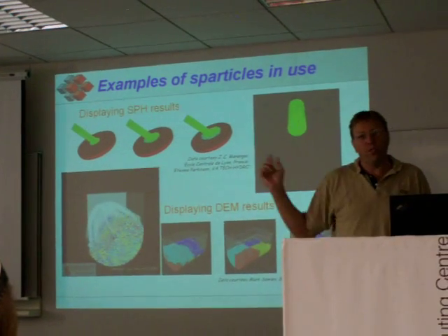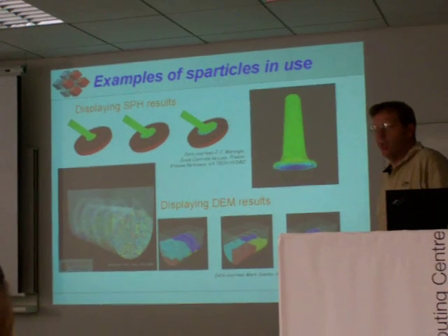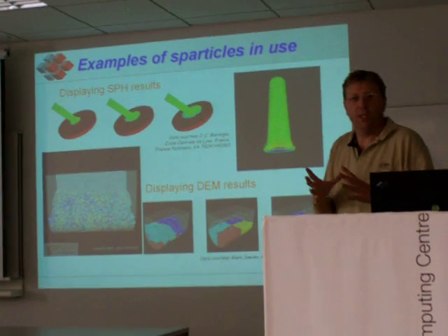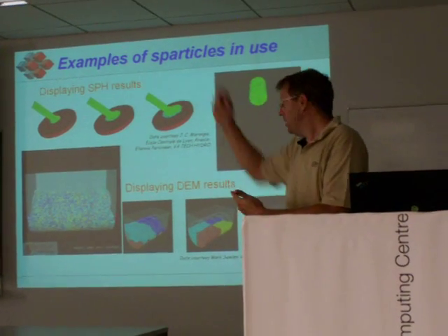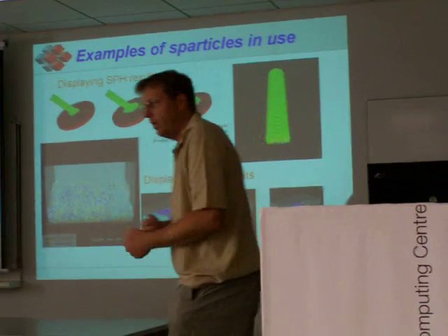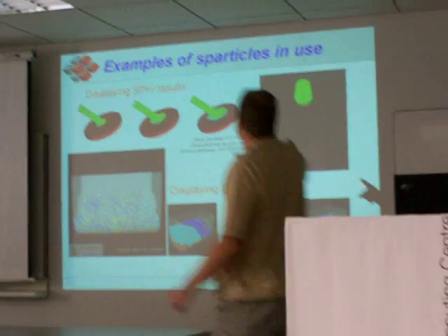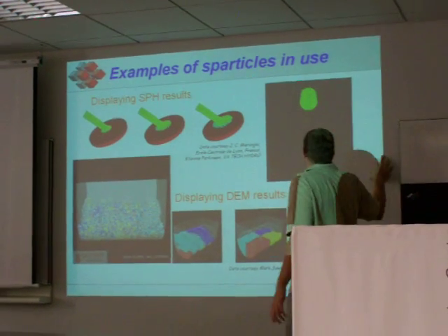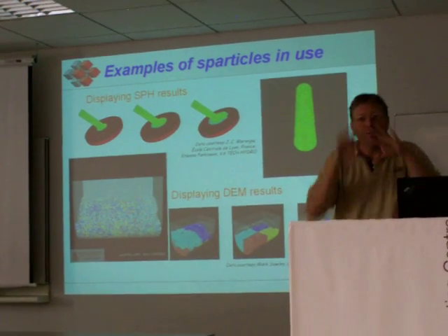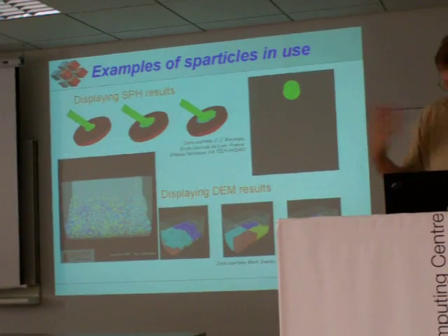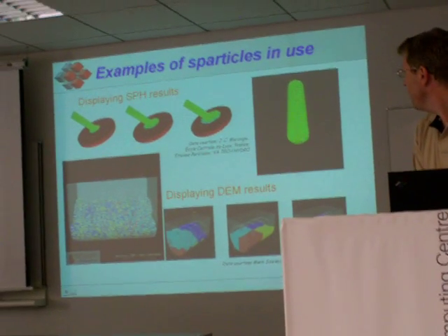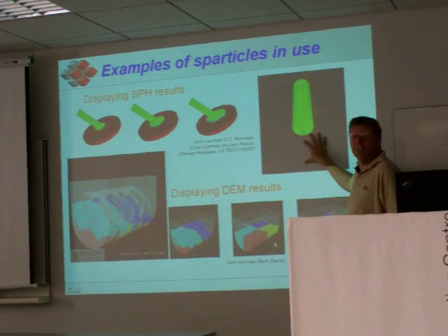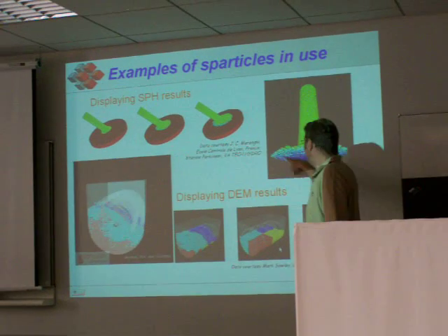This becomes implicitly more difficult to manage because when you've got a mesh, you know that this node is connected to that one. So when you do a finite difference or finite volume calculation, you take the differential of all the nodes around you, get a new number, and then you just march through the simulation. Here, particles can go whoosh, they can fly off over there. Now this one interacts with that one, and this one interacts with that one. So you've got this constantly evolving tree structure with all the particles moving around inside it. Much more difficult to manage the data, but in theory, computationally more efficient. The bad news is that it's also computationally much less accurate.